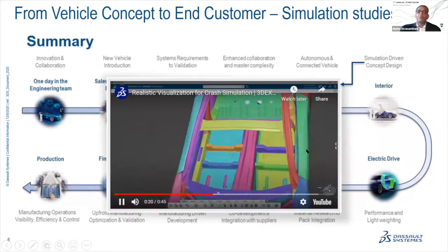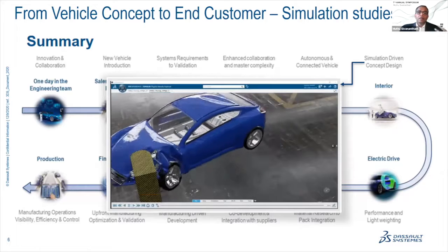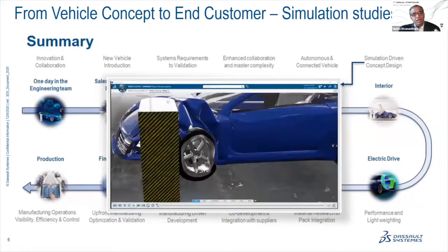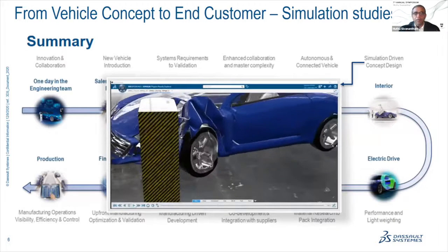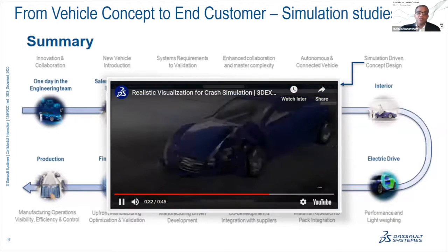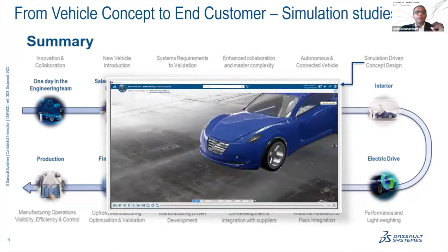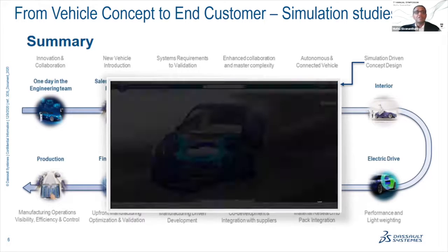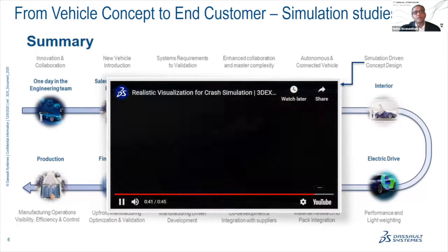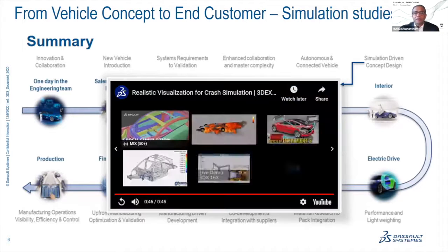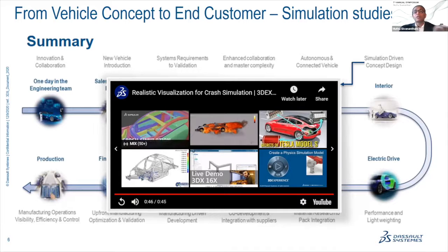From a CAD model that was generated, the simulation engineers are able to create an accurate representation as a finite element model. Now they can use that to do crash testing. It tells you about the structure, the crumple zone, and various factors that you can test well in advance before you make even a single part. You can do structural analysis and strength analysis, and make sure the humans riding in those vehicles are safe. Would they be able to take that kind of jolt?